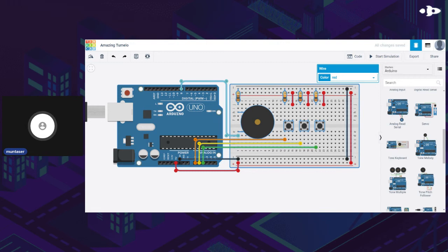All right, so just real quick, let's go over how the breadboard is laid out. So if you see a breadboard like that, the essential layout of the breadboard is, you see the bottom rail. The bottom rail is all electrically connected. So if you connect anything to one of these holes in the bottom rail, it means you're connecting it to any other hole in that same rail. The same goes for the black rail, and also the same goes for the top two rails over here.